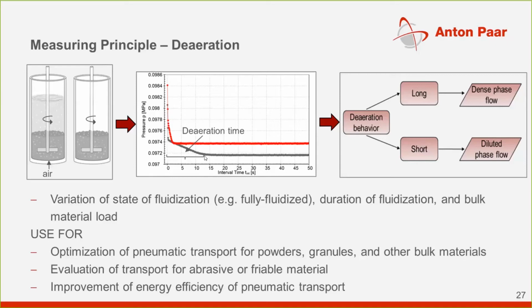The deaeration can be interesting, for example, when pneumatically transporting powders or bulk solids. But this can also be interesting to evaluate the transport for abrasive or friable material, or improve the energy efficiency of pneumatic transport. But this can also be very interesting if you are, for example, filling samples that have a very high air retention capacity, because this will indicate that you might have to wait 12 seconds before continuing filling. So we'll fill it in the first step until it is full, wait 12 seconds, and then continue filling.